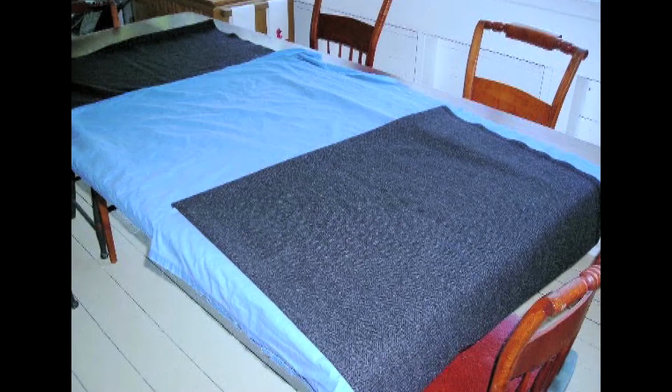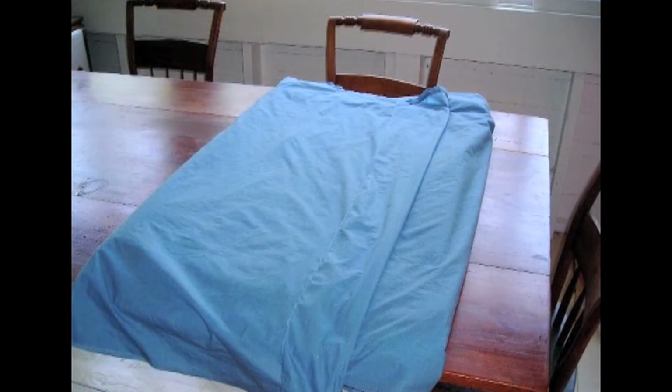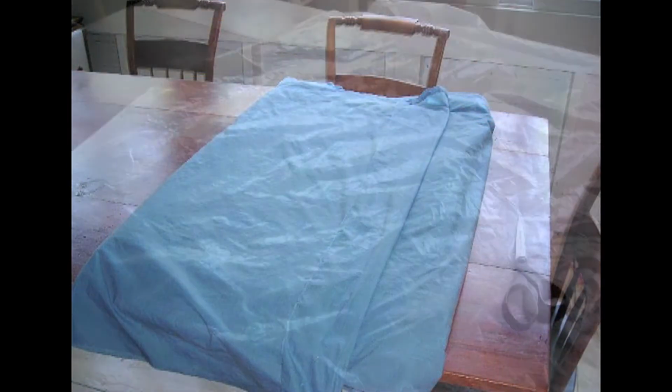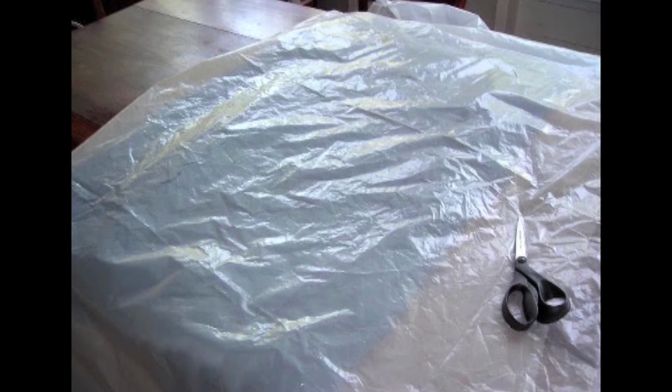In case of woolen fabrics, London shrunk means the fabric is pre-shrunk in case of wool. And in case of synthetic fabrics, actually this pre-shrinkage is not there, but they are finished at a very high temperature, equal to their transition temperature, so that if you use any temperature more than that, the fabric is going to distort.